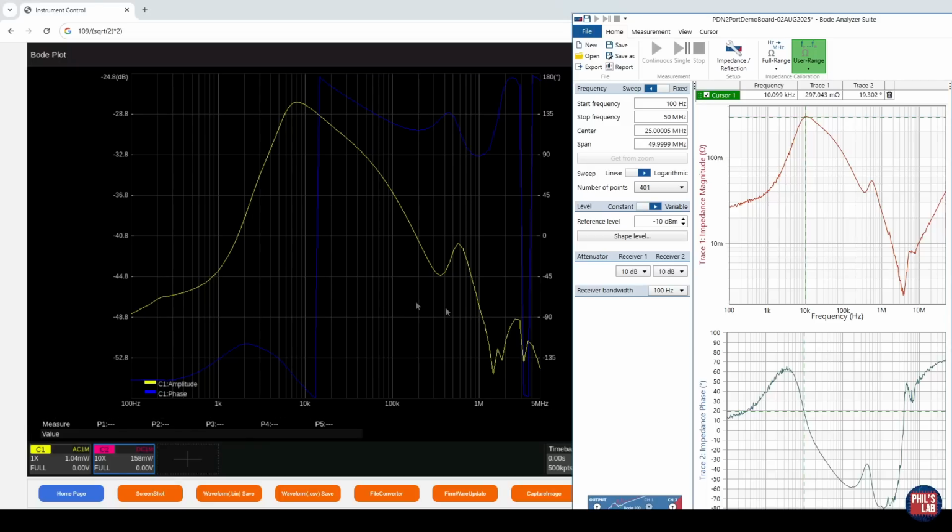The cool thing is we have shown two different methods of extracting essentially the same information, and we verified what effect our PDN impedance has on the ripple effects seen at a particular point on the printed circuit board, at a particular point at the power distribution network. So even if you don't have a Bode 100, you can also perform these measurements using a signal generator, a current sink, and an oscilloscope.